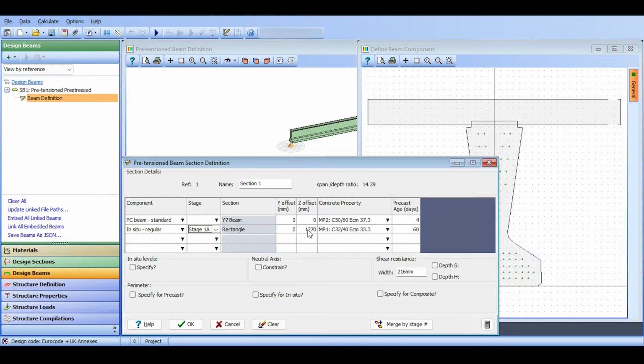Now for the offsets, those are perfectly fine. Offset means you can move the slab. For example, if you click on offset here and say 500 and tab out, you can see the slab moves 500. But of course, a 0 means the slab is dead in the center of the centroid of this beam. You can see that this is the central y-axis. Of course, the z-axis is offset up. This has been automatically calculated. You could change it, for example, 1070, then it's inside the beam. Of course, it doesn't make any sense. So 1270 is the offset I want.